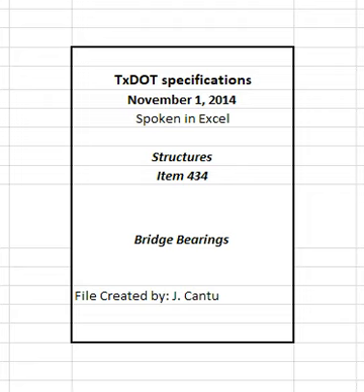3.2 Sliding elastomeric bearings. Electronically submit shop drawings for the complete assembly before fabrication of sliding elastomeric bearings in accordance with the plans and Item 441, Steel Structures. Provide a bearing layout with the shop drawings. Finish the steel top, sole, plate surface interfacing with the stainless steel sheet per Section 434.2.2.2.1, steel top, sole, plates. Provide this finished surface flat to a tolerance of 1/32 inches.